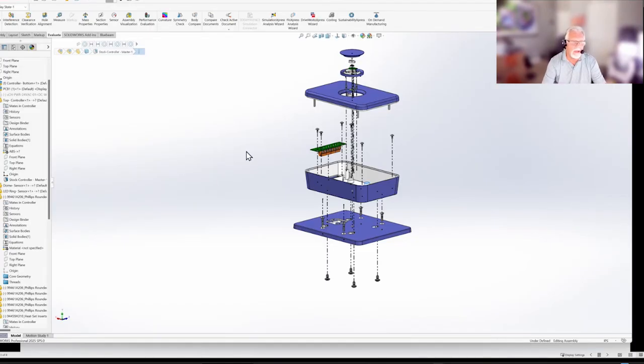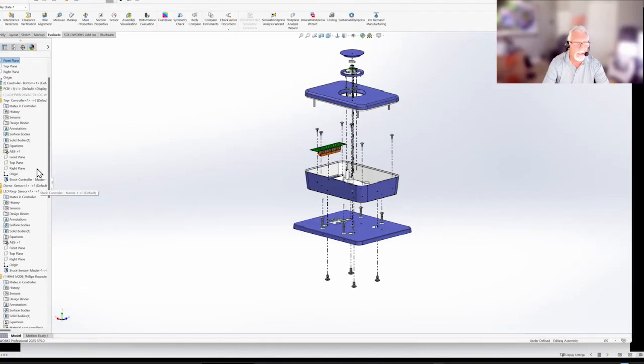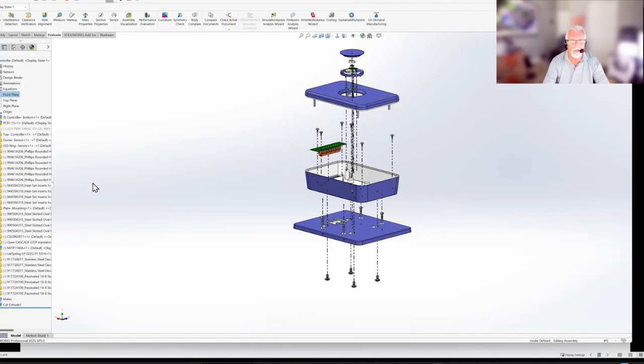So, and now the other thing is, it's real annoying. We get this area of my menu area open a lot. So if I hit the Shift C, that collapses it all. So that kind of gets it all cleaned up. Next, because I've got a lot of things here that I want to show, I'm going to go ahead and we're going to do some things in, I'm going to hit my R key because I'm going to bring up my sketch.